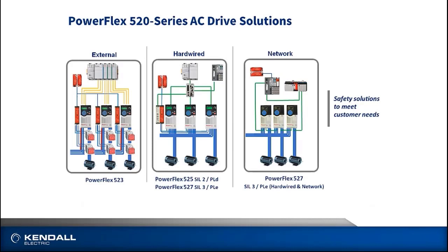From there, with the advancement of safety over Ethernet, we now have safe torque off over Ethernet on drives like the 527, which gives us a higher safety rating than some of our other hardwired options, but also makes it a lot easier to integrate and use.